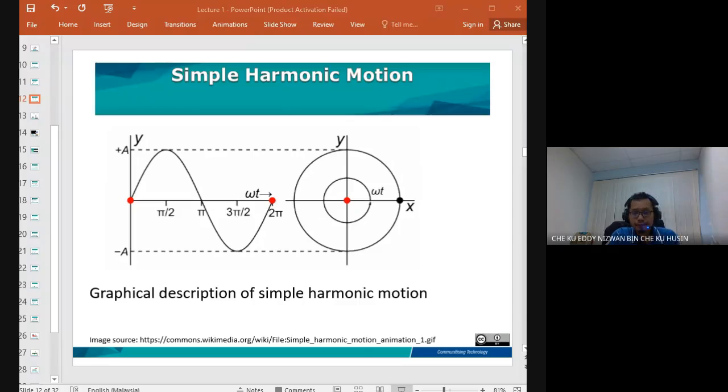But in actual measurements, the value of velocity is actually one of the most important, because velocity is one of the most stable values compared to displacement and acceleration. That's why in most standards, the ISO standard and the Energy Institute standard normally use vibration in units of velocity.